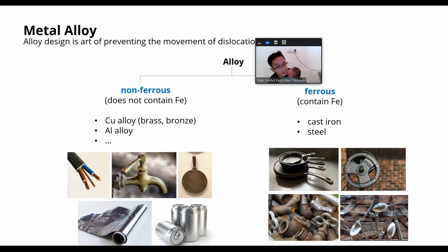Okay, the top here is made from 5000 series. So you can see, even though this drink can is just a simple can, there is a lot inside in terms of material. The body is different from the top of the can, this peel-off part, which is normally made from what we call the 5000 series. The body is 3000. This is 1000. The aluminum foil is 1000.